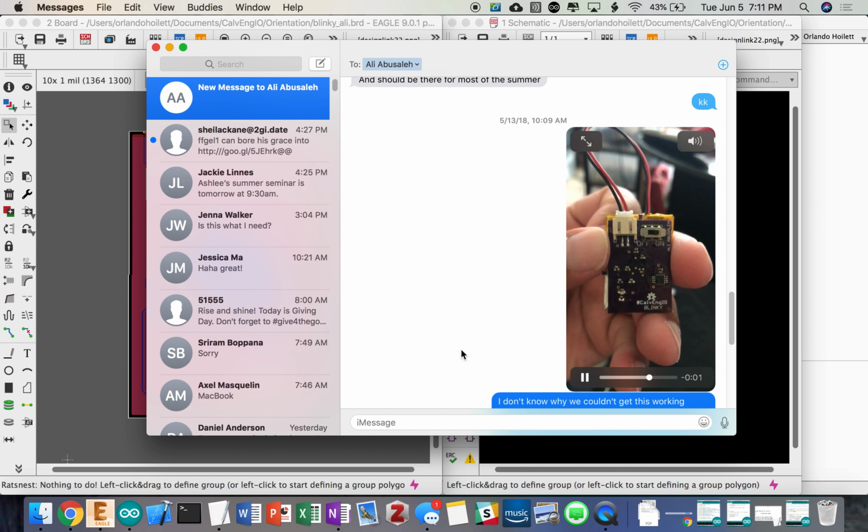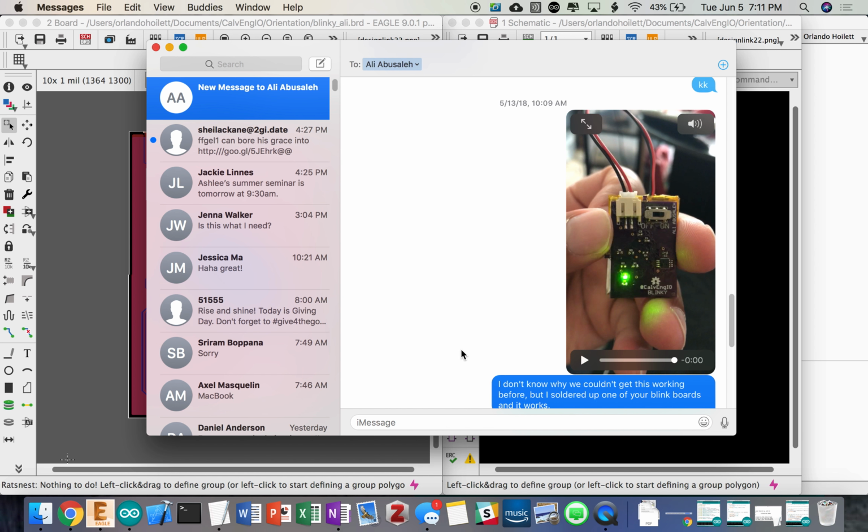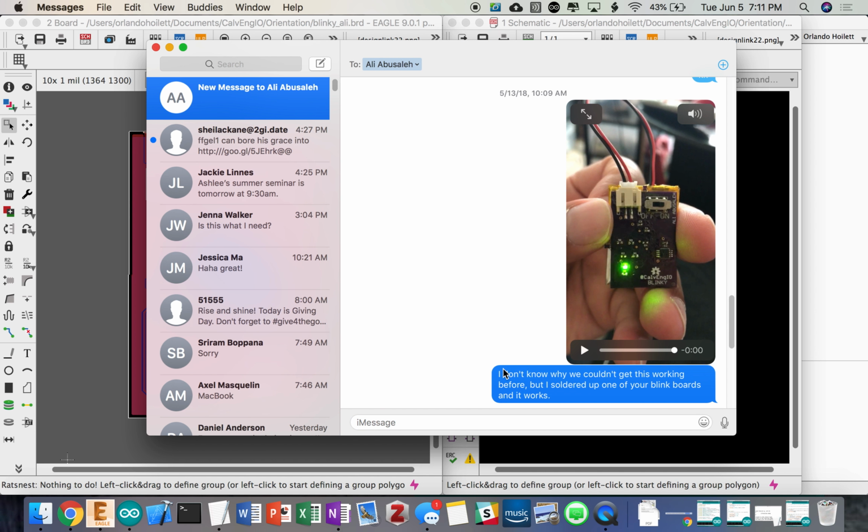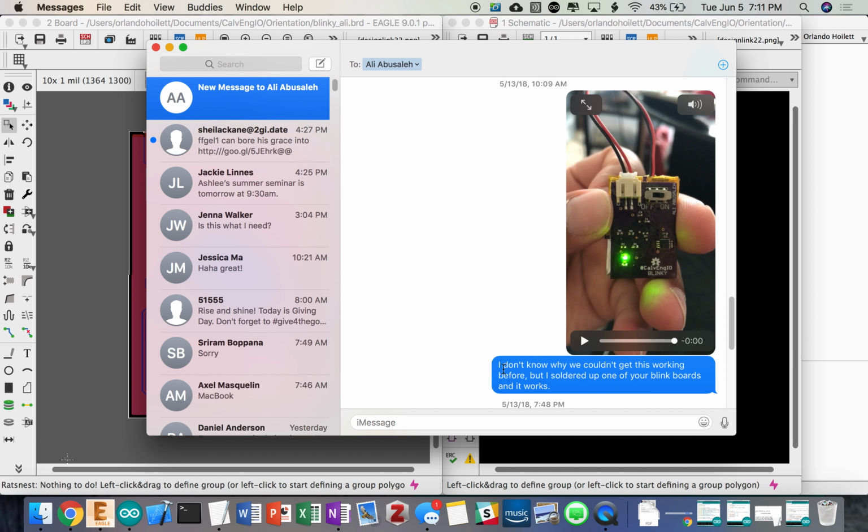Are you guys able to print on campus? No, we'll actually send this off to a company, so it gives you a small guideline of how big to make the boards. Because this company is $5 per square inch, so I think all these boards cost like $5 or something, with free shipping. But we can do some printing on campus. There's BIDC, Bechtel Innovation Center, and they mill the boards. Personally, I don't really like milled boards, so I just send them off to get printed. But it's kind of up to you.